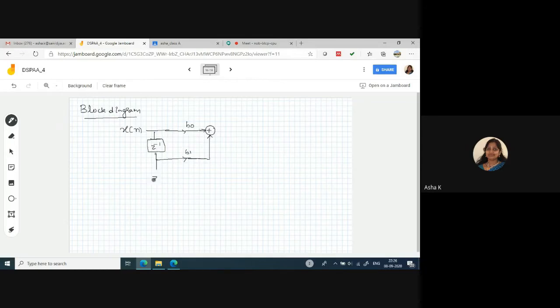Again, one more delay unit is used here, the second delay unit. Then after this, I'll multiply this with the second coefficient, that is zeroth coefficient, first coefficient, and b2, and again this will be added here. So it goes on.